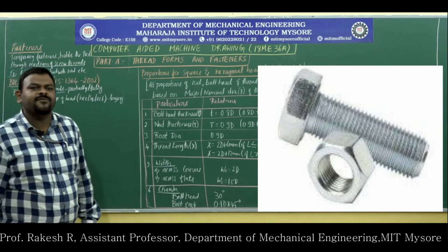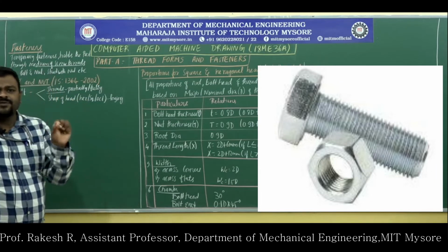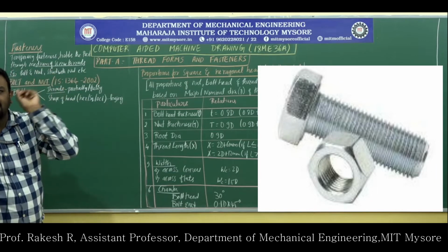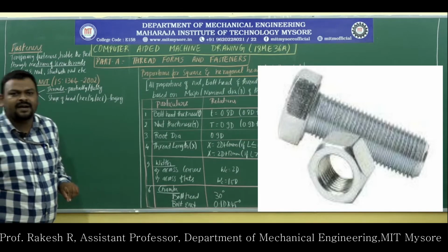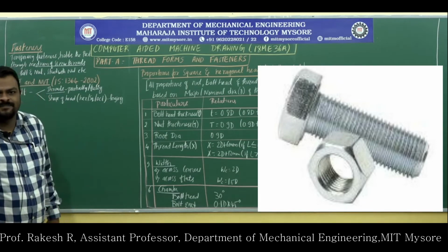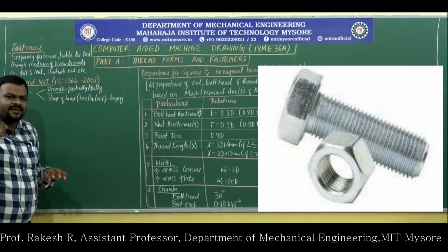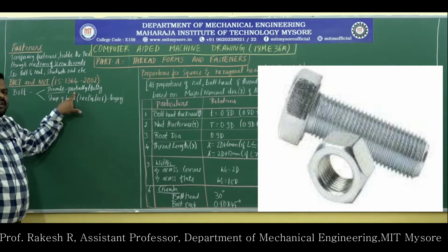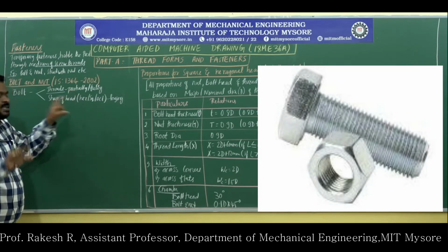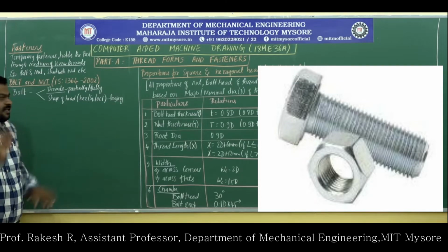That is the convention for a bolt. M12 represents the metric thread of 12 mm diameter, into 80, which means the length of the bolt is 80. Like that we will specify the bolts. And remember, every bolt will have an external thread as well as a head shape. When it comes to a stud, there is no head.